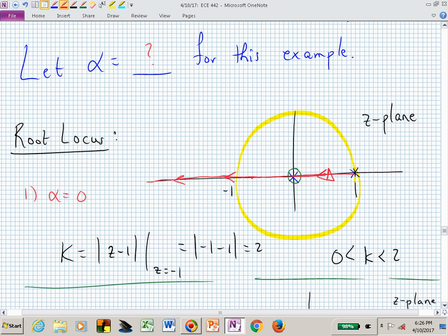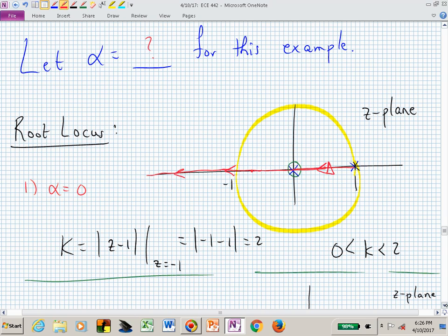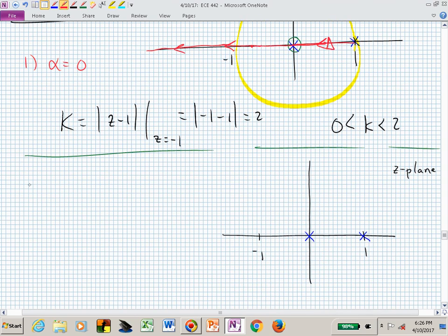What are some other choices for alpha? What if I made alpha equal to -1? What does that do for me? Now I'm locating a 0 there. Again, I'm trying to think, where do I want to put my 0 because I'm now introducing a PI controller?